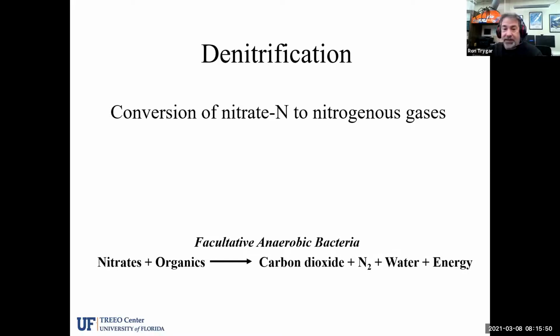So we'll talk about that a little bit here as far as how to monitor the denitrification basins, or where we're purposely trying to have it happen, or if it's happening in a basin where you believe it should not be occurring. Let's say you're getting denitrification in a clarifier and you're experiencing pop-ups or problems in the clarifier, then we can use ORP to kind of see if we're in the range for either an oxidative situation or a reducive situation. So we'll talk about that.